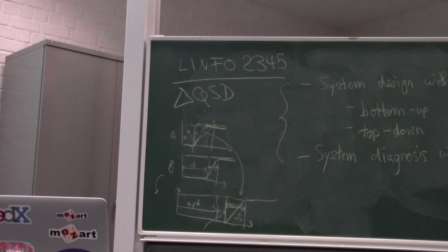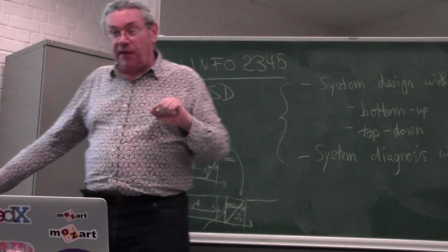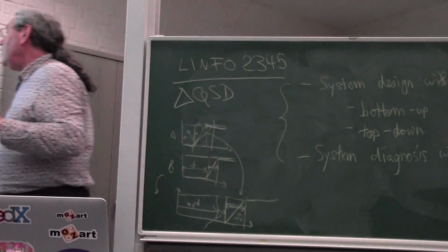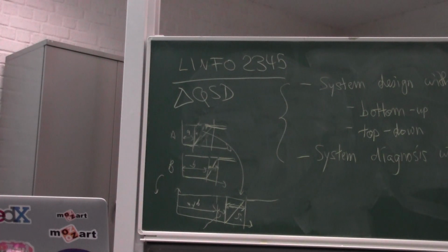So the spread of the output is going to be the maximum of the two input spreads, and the minimum delay is going to be the sum plus a little bit more. So that's that back of the envelope, huh? You don't need to do so much computation. So that's kind of neat, huh? The delay is just a little bit worse than the sum,